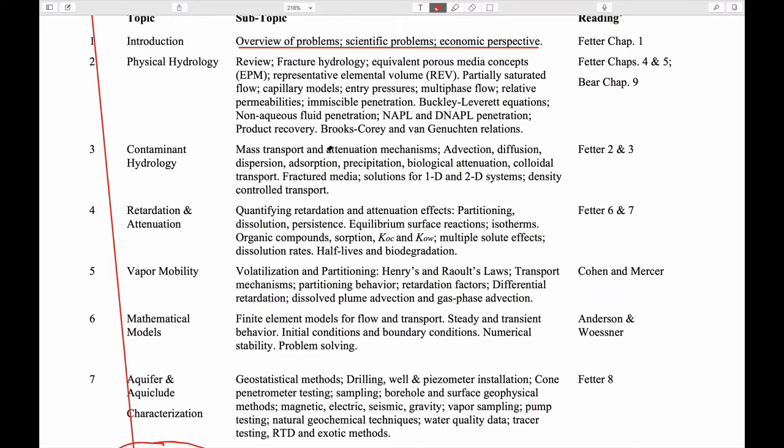First of all, following on from Geosciences 432, groundwater hydrology, we'll continue talking about physical groundwater hydrology. I guess the difference was that instead of talking about it broadly in terms of water supply, we'll talk about multi-phase flow, where you have two fluids which may be either miscible or immiscible relative to each other. And so our main concentration on physical hydrology will be talking about multi-phase flow of oil and water, for instance, or air and water. They both behave in the same way.